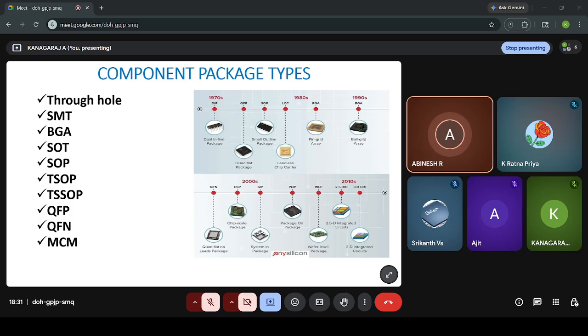In a ball grid array, the chips are mostly square in shape, and at the bottom, instead of pins there are balls. The balls act as pins, but they are not placed randomly. They are located in an array. An array is a set or collection, in vertical and horizontal rows, with a large number of balls acting as pins for the chip.